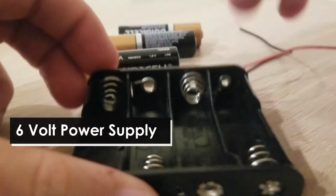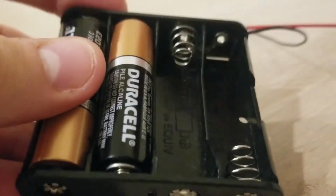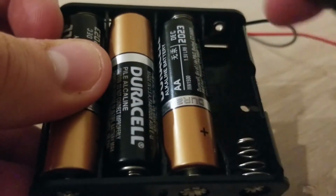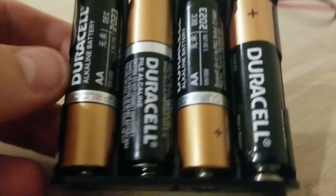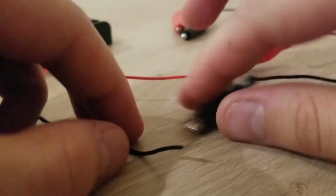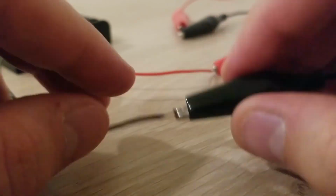You are also going to need a 6 volt power supply, which will ideally consist of 4 AA batteries linked together in series. This supply will work well for most situations on this board, but stick around for a small note on choosing your power supply in just a second. Once you've gathered these supplies, attach your lead cords to your power supply, and you're ready to start making circuits.